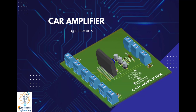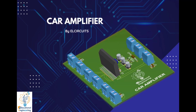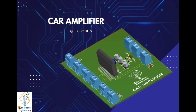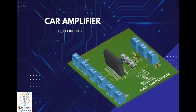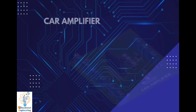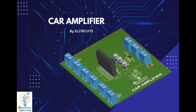So, this is a 14 volts, 4-channel 200 watts MOSFET quad-bridge power amplifier. It uses a TDA7850 IC in a quad-bridge mode to drive 4 power speakers. This is originally made by Electronic Circuits. The circuit provides a total output power of 200 watts, with good sound quality, powered from a unipolar 14 volts power supply. Now, let's go to Altium.